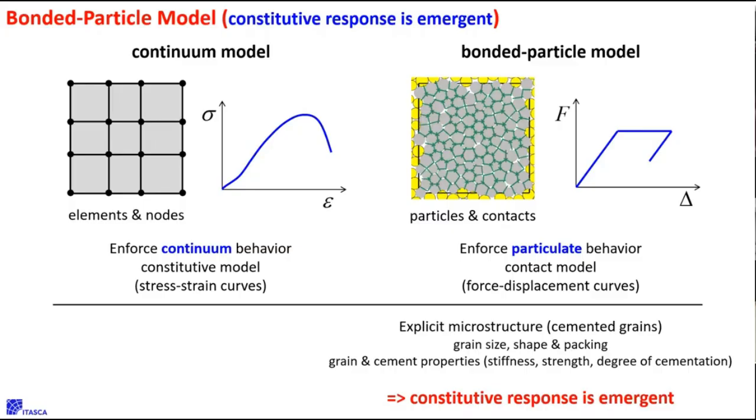But it raises all kinds of other weird points. One, no one can ever do a lab test on an 8 meter by 4 meter cube of the real rock. And at the excavation scale, if you really were to take out an 8 by 4 meter cylinder of rock, when you tested that, it would not behave like a laboratory scale cylinder of the same rock. And the reason is because the laboratory scale cylinder has been selected to be a perfect intact hunk of the material.